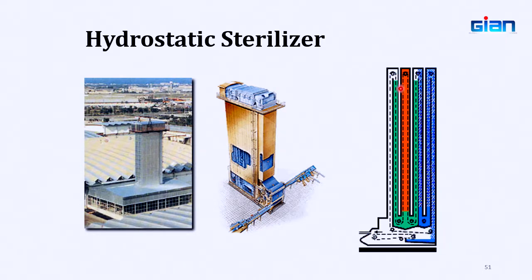And then this is hot water, but this side white and this side blue are low temperature water. So then using the chains or the conveyor belts, you allow cans to come in on that belt, and this belt is not running horizontally. It is going vertically up, coming down, then going up and coming down through these water columns or steam columns. So maybe let's say a can comes from this side or this side, and then it goes up and goes in this hot water, slowly getting heated, and then goes to the steam column, it's getting heated, then comes out.